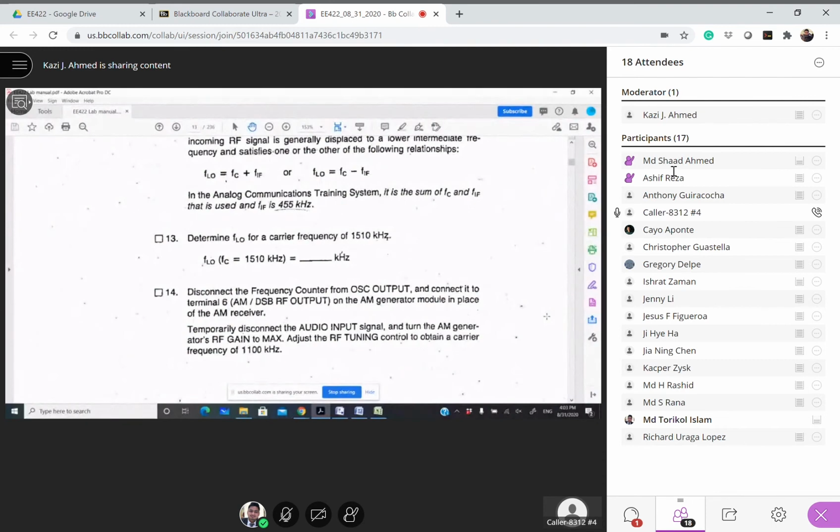So, you bring up a very interesting point. Let's say we are sending two carriers. One is 1000 kilohertz, and the other one is 1200 kilohertz. Now, when the local oscillator is at 1455, it will get the first carrier, so now it can hear whatever message is with the first carrier. Now, if you change the local oscillator to 1655, it is now hearing whatever is with the second carrier, right?